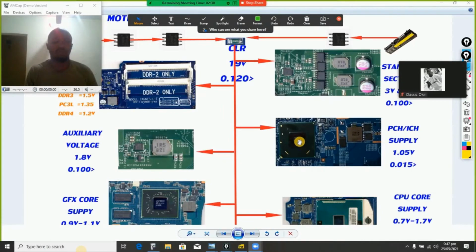Once we've confirmed the voltage, we've escorted the voltage to a point where we are sure it's going to the PCH, and once it gets there and it's not working, then it's left to the PCH. There are some faults that are not fixable in a laptop. If there is an issue with these chipsets, this particular one, they are still fixable if they are faulty. Once you have your VGA, if you have confirmed they are faulty, or let me say like 15% of cases of motherboard faults are going to be chipset issues, there is nothing but to replace them.